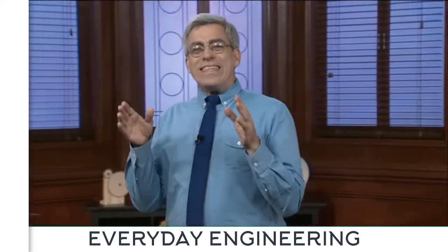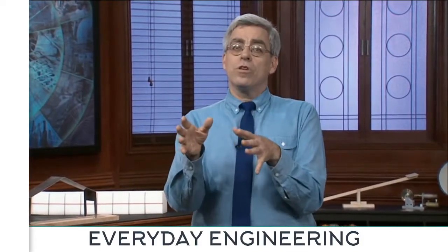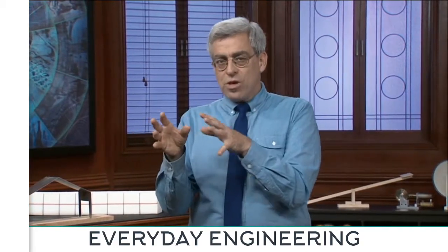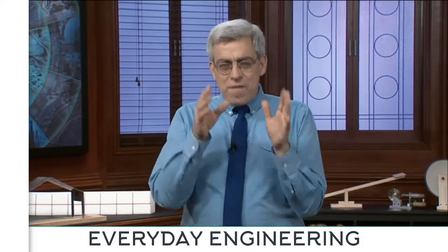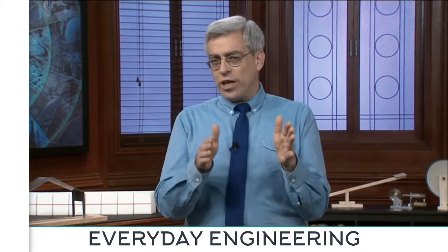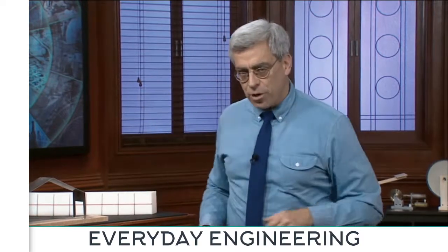The first is called dead load, the weight of the building itself, including structural elements like beams and columns, non-structural components like shingles and windows, and permanent fixtures like bathtubs and kitchen cabinets. Dead loads are fixed in both position and magnitude. They're usually associated with known quantities of physical stuff, so their magnitudes can be determined quite accurately without a lot of detailed guidance from the code.